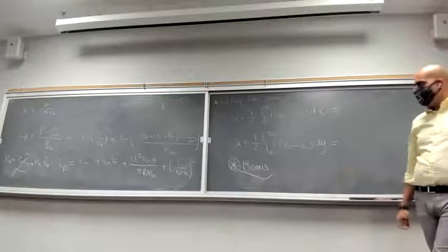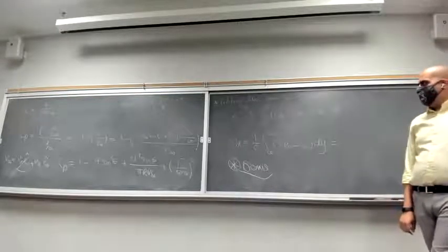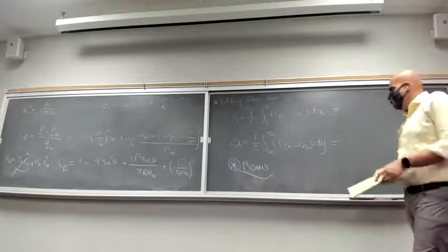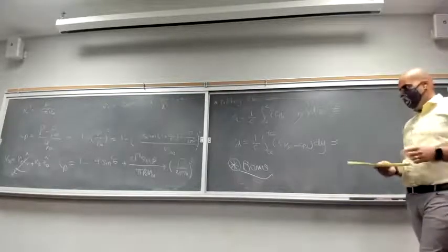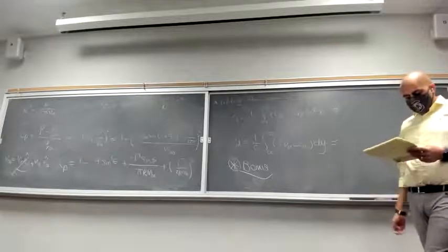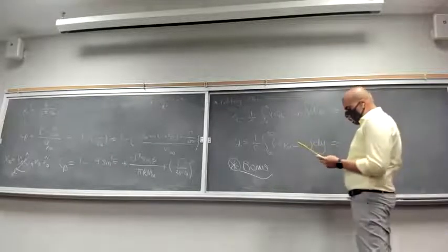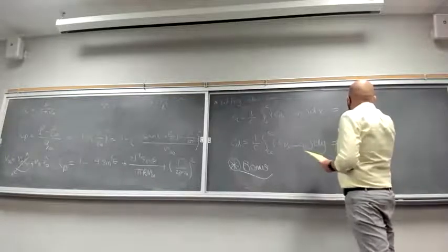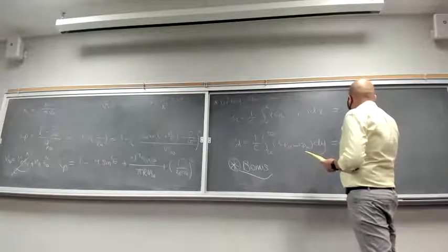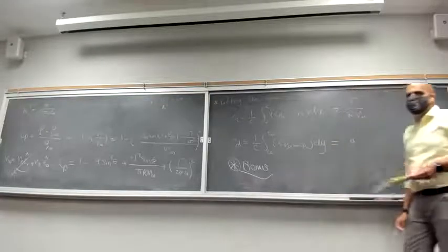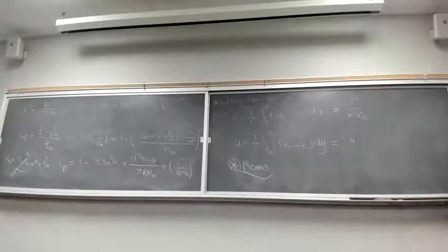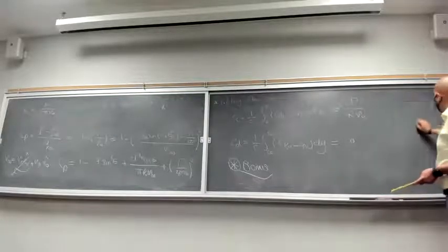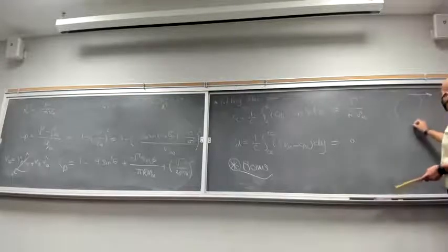Okay, so if you can work on this calculation, the integral of Cp, to get the final Cl. Eventually, what you're going to get for Cl is going to be gamma divided by r v infinity, and your drag coefficient is going to be 0, right? What does this mean? This means that for a rotating disk,